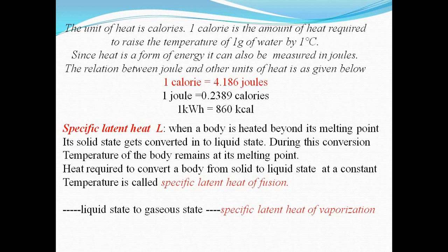Okay, so now in which there is a change in the state of the substance, in that system consider the specific latent heat. Heat required to convert a body from solid to liquid state at a constant temperature is known as specific latent heat of fusion or liquefaction, and if it is changing from liquid to gas, then it is known as vaporization.